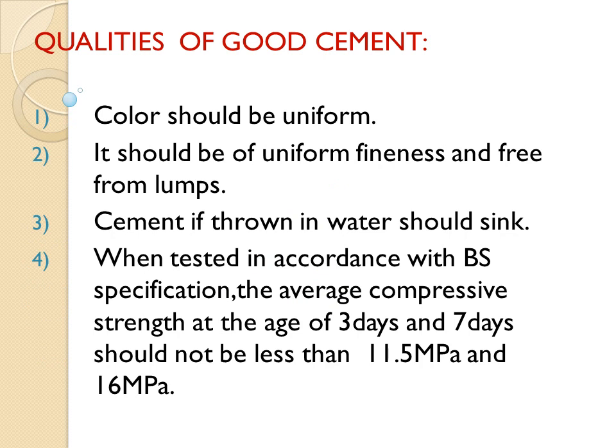Let's talk about quality of good cement. The color of cement should be uniform. It should be of uniform fineness and free from lumps. Cement, if thrown in water, should sink. When tested in accordance with British BS specification, the average compressive strength of the cement at age of 3 days and 7 days should not be less than 11.5 MPa and 16 MPa respectively.